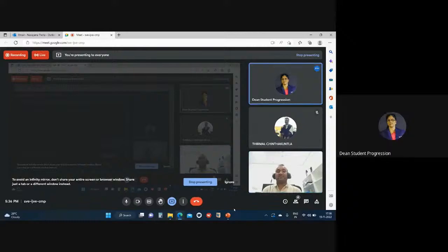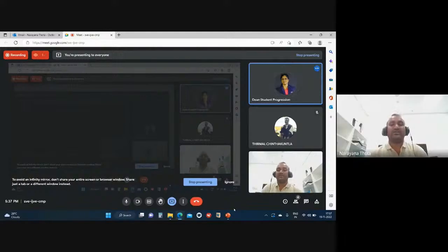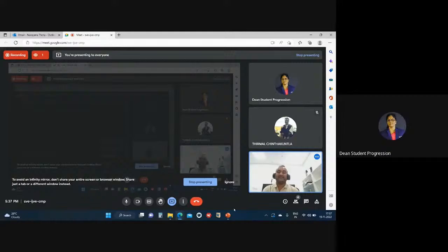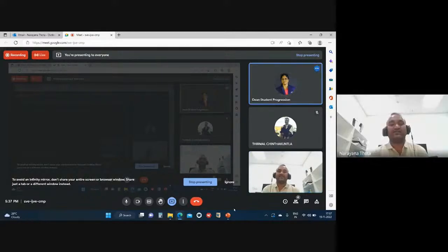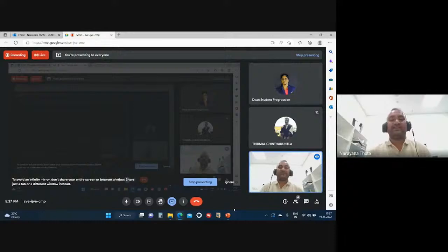Okay, sir. Another question: if there are two band offsets, conduction band offset and valence band offset, and suppose the conduction band offset is a bit higher compared to the valence, can the device show good performance? Generally, we start with Fermi level alignment. First, we align the Fermi levels. From that, they calculate the conduction band offsets and valence band offsets.